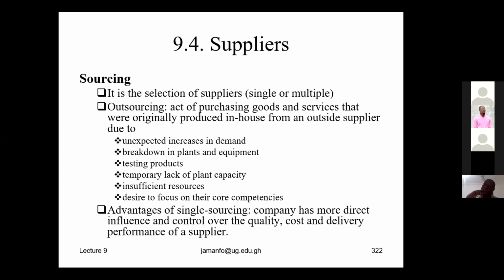Yes, just in time will solve it. But again, just in time cannot be in isolation. I think last week I did tell you that with just in time, you let the person know that you're operating on just in time for this component. The concept is all about shifting that responsibility of inventory keeping to your supplier by making the supplier aware. And the supplier buys into the idea because he knows that when the products are there, you are going to buy it. So just in time solves that inventory problem to a large extent.